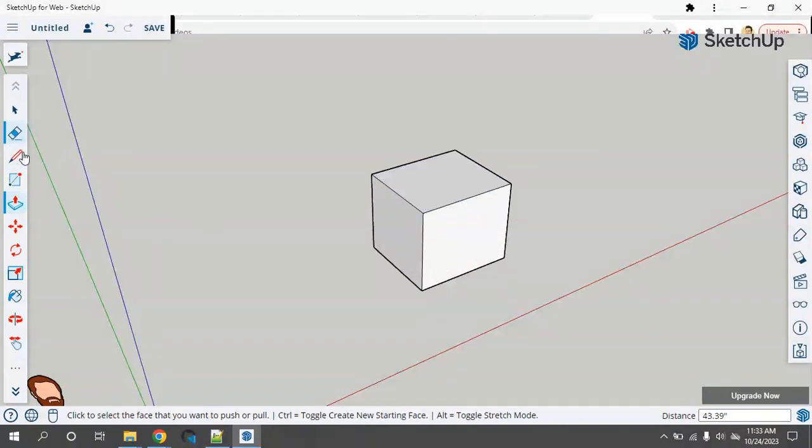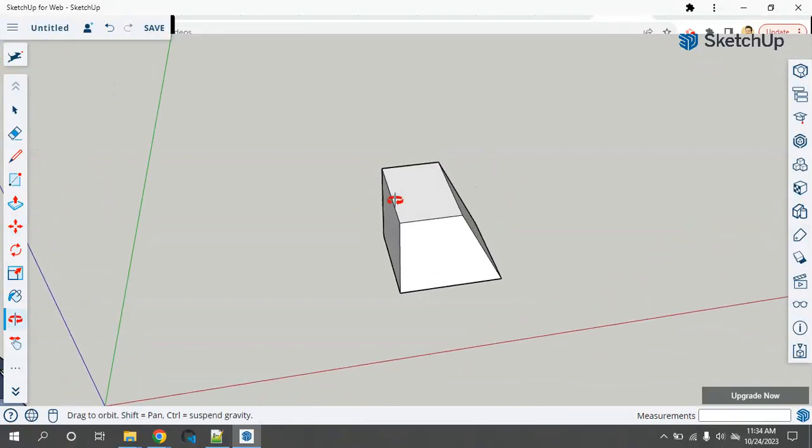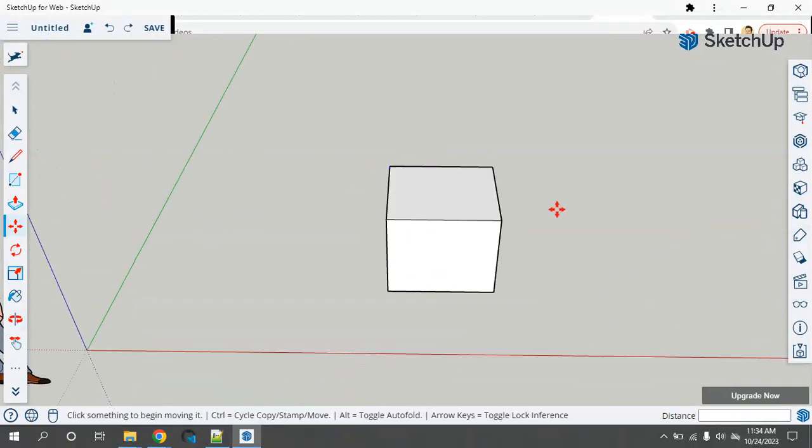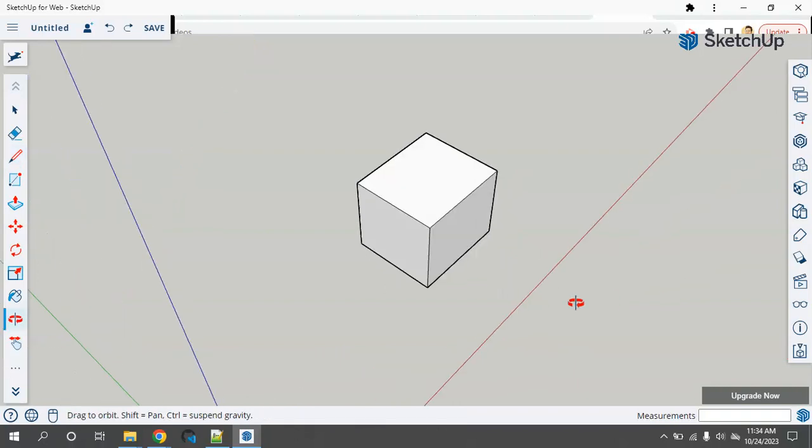So this Move tool is really powerful. As I said, you can shrink that like that, and we can start creating some wedges. Or if, say, we were to grab a line, notice that SketchUp really wants to help me out with what are called these inference points here. It's going to try and tell me a little bit where the ends are, where the middles are. Even if I drag to the middle of something, this usually works better with circles. We could figure out where things are nice and evenly.